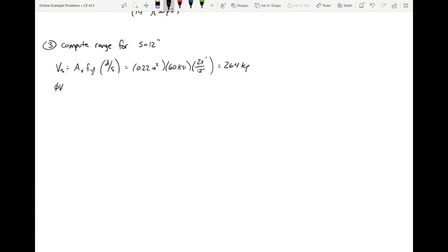And so the entire shear capacity is going to be Vc plus Vs. Now Vc, we already computed that. Vc was 31.88 kips. We don't need to apply phi here because we already did, but we do need to apply phi to this one. So just make sure you're keeping track of proper bookkeeping. You don't need phi for the Vc because you already have it, but you do for this. So 26.4 kips.